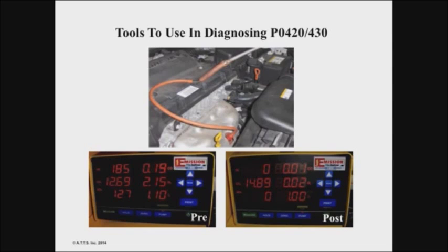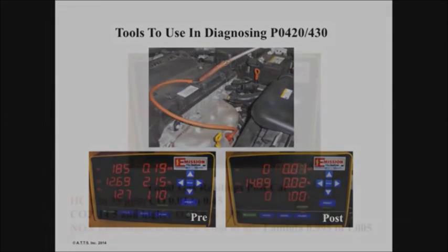I'm going into where the air fuel wide range sensor is. I don't care if I'm not in fuel control anymore. You know why? I'm seeing what the exhaust readings are there and what the cats are doing at the tailpipe. Okay, so there is a pre-cat, there is a post-cat. Look at the difference of those readings drastically, so apparently this one is good.